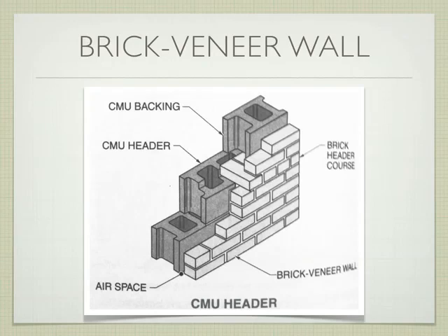You're eliminating the little metal ties that are tying the bricks together, and in this case, there's a special concrete masonry unit, right, that has a notch that's left out. We're going to put in a header that runs this way that actually will tie in, and the next concrete masonry unit goes on top of that. So we're using the bricks themselves to tie into the wall, right?